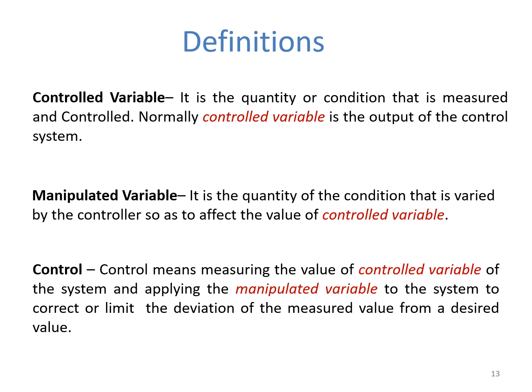the desired value. For example, if I have a heating system and I want a temperature of 80 degrees centigrade, that is my desired output. Now if I give some input and get an output temperature of 60 degrees, there is a difference of around 20 degrees. So the output you have got is not desirable, and it has to be manipulated.